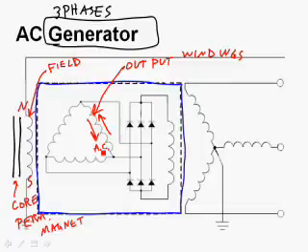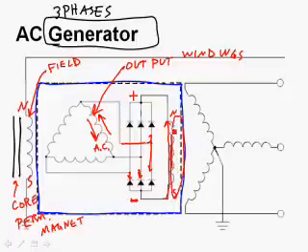But just like in a DC alternator, we're going to pump this alternating current through diodes. So we'll essentially rectify it. We'll turn it from AC into DC. So current flow is going to come out here. Electrons can't go with the arrows, they're always going to go against the arrows. So we're going to get direct current. So amps are always going to go through this field in one direction. So one side will always be north, one side will always be south. And of course, if we run amps through a wire, we get lines of flux.